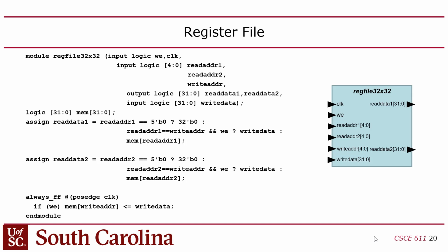Okay, so that's the register file. I don't know if that's the best way to do it. Now, when you synthesize this, it's going to get synthesized as an array of flip-flops because there are no RAMs on the FPGA that will behave this way.